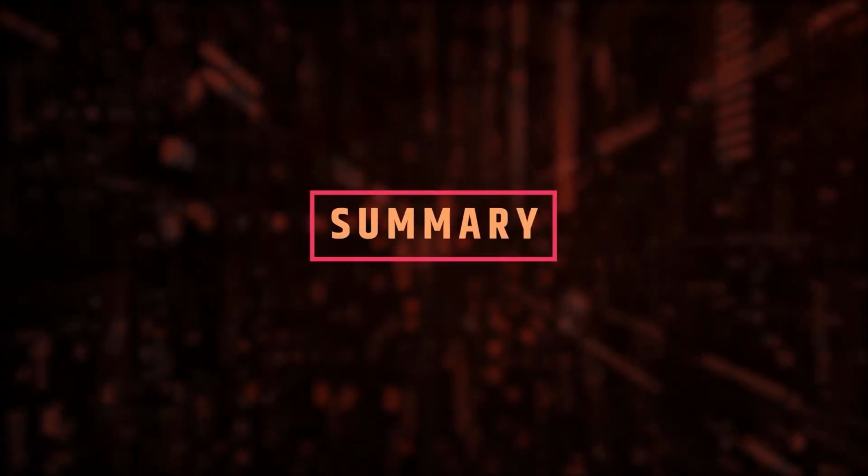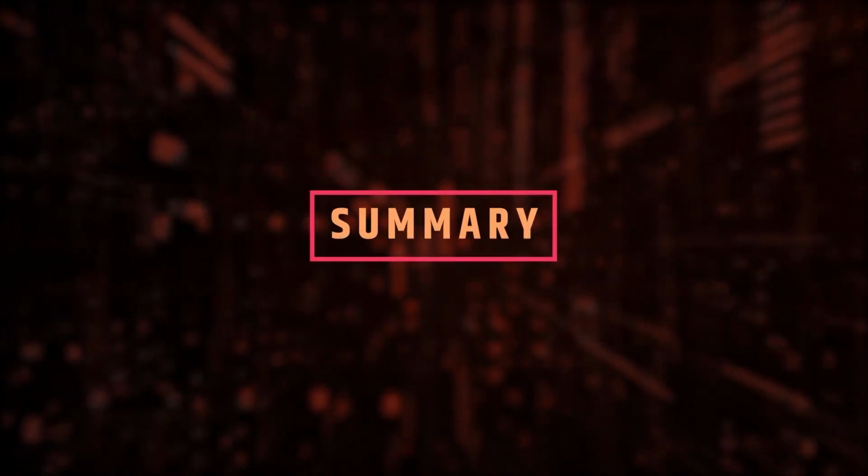Before we wind up, let us have a recap on whatever we discussed so far. The registers are sequential circuits which can perform in different modes: serial in serial out, serial in parallel out, parallel in parallel out, and parallel in serial out. Then we learnt about the bidirectional shift register, which can shift data in both directions. At the end, we learnt about the universal shift register, which is a general purpose register.